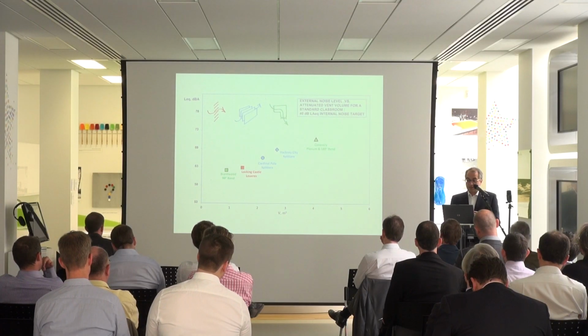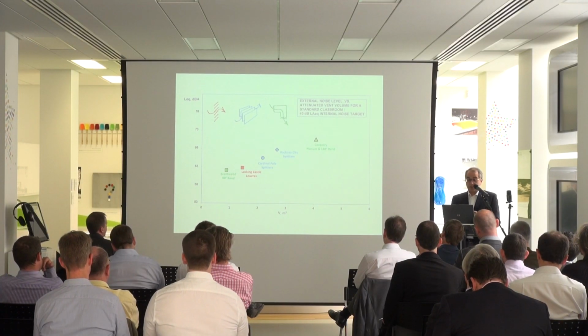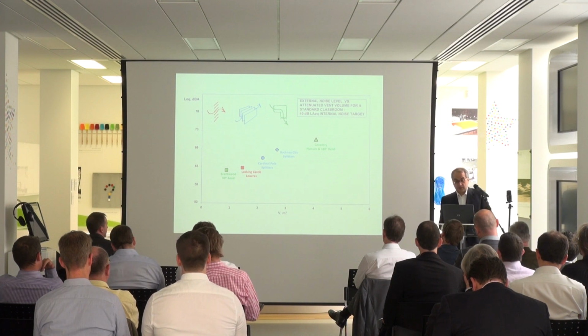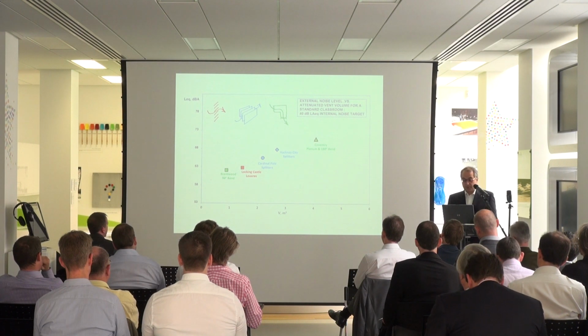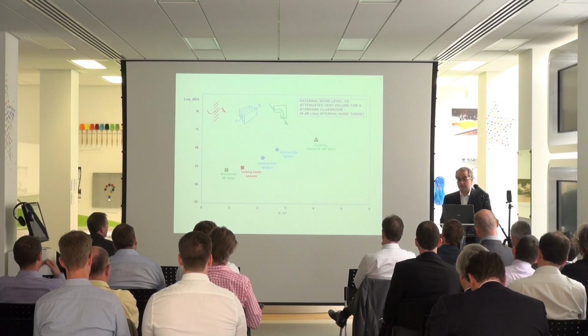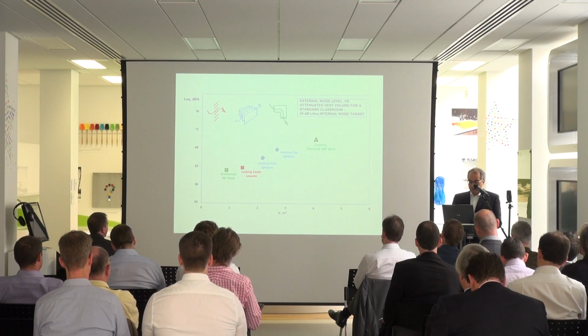What we can see is that as the external noise level increases, the volume of the attenuator also increases to achieve the same target internal noise level. So basically, in noisier parts, we need larger attenuated volumes to meet the standard internal noise levels.